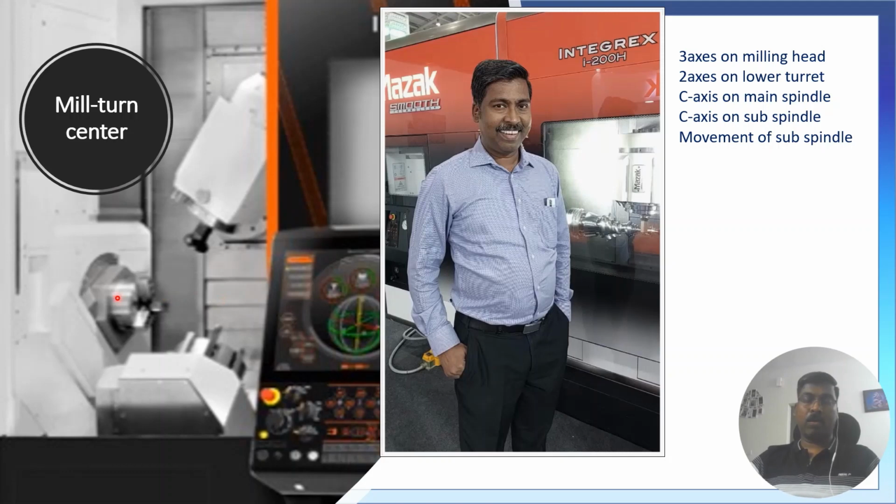That means on this machine there will be another spindle on the right hand side, and the sub spindle will come to the main spindle to do a job transfer. So whatever part is there in the main spindle, once the main spindle operation is completed, sub spindle will come and pick that part, or vice versa.